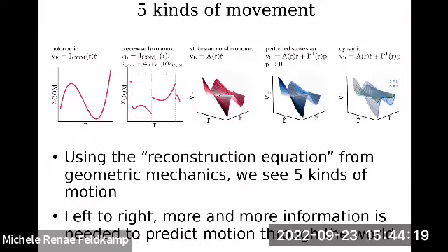But it turns out that if you look at the structure of that equation, body velocity is some shape-dependent matrix times shape velocity. That can happen even if that matrix there didn't come from being the Jacobian of any function. And that's what happens in friction-dominated regimes. There is no function for which that connection, as it's called, is a derivative, but that function still exists, that AFR. And you get a lot of structure that you can learn about how a system moves.